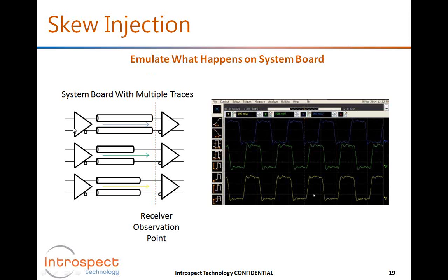So in this picture here, we show how certain channels on a PCB system could have different trace lengths. So we have the driver, three differential pairs out of the driver, let's say on a D-PHY driver, and then 3 differential receivers. The receiver only sees the signal here. So even if there's a perfect transmitter D-skew or transmitter skew between the 3 lanes, once the signal goes through PCB traces, each receiver will see a slightly different delay.